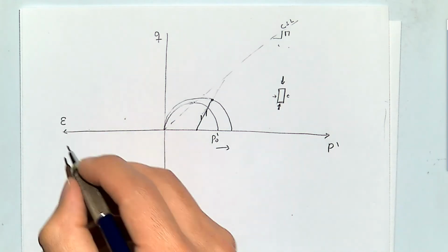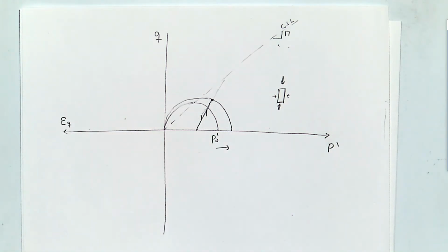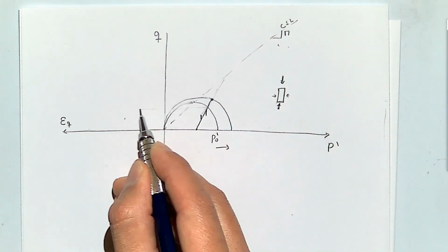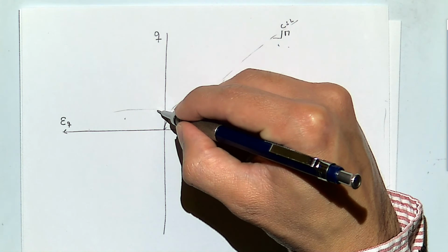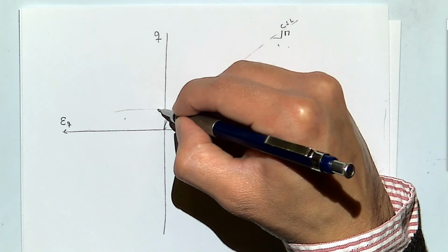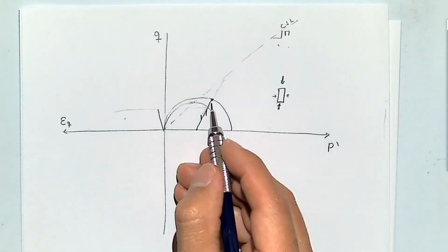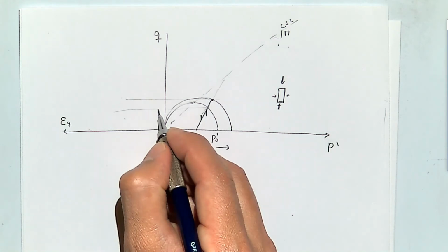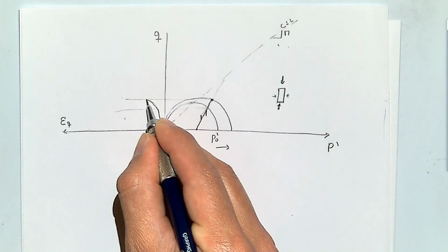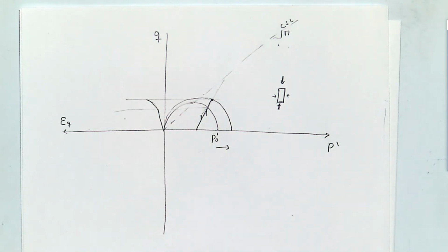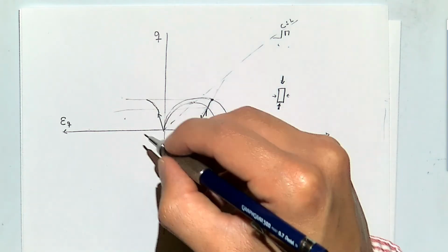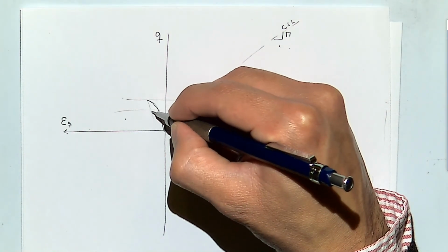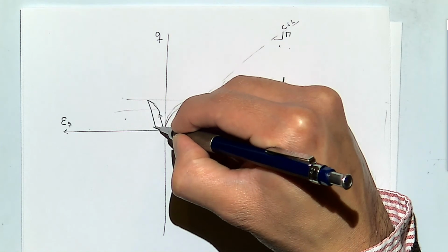If we take a look at here, the strain in the deviatoric part looks something like this. We go through, first is the elastic component. Once we go through the plastic component, then this one starts to curve. If we do an unloading, we're going to assume that we come back on the same curve, or the same stiffness that we had before, and we get there.